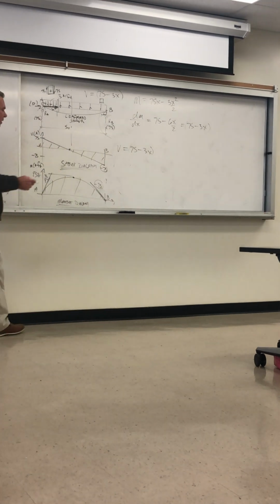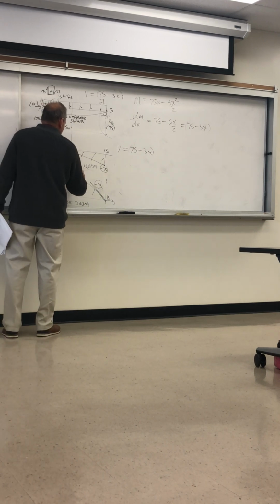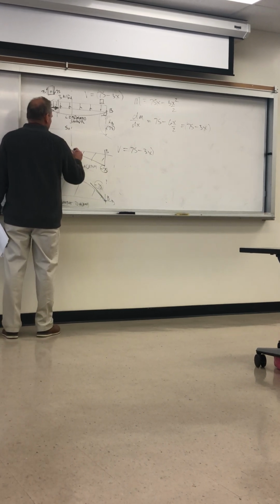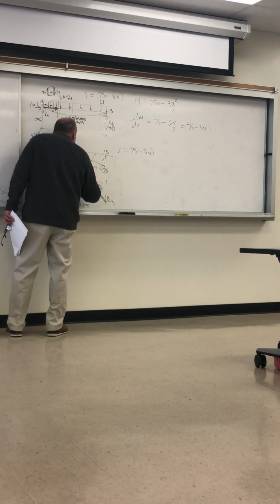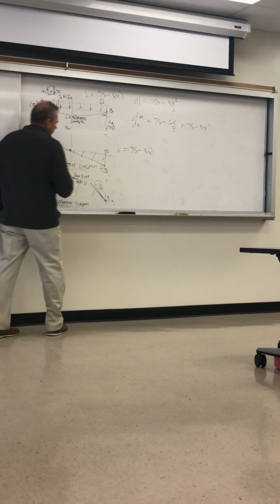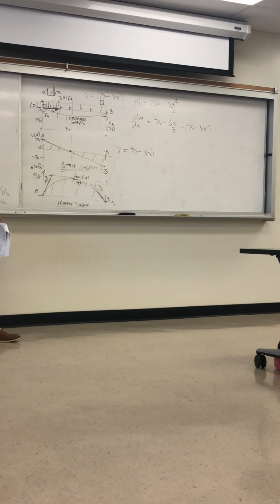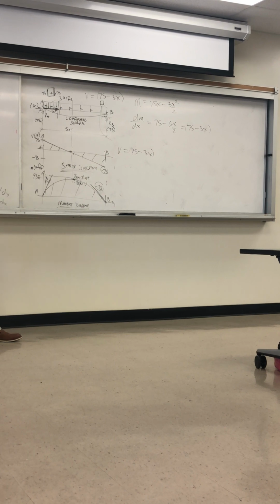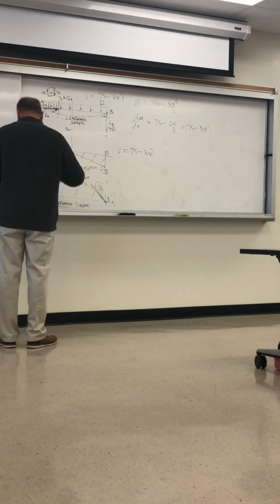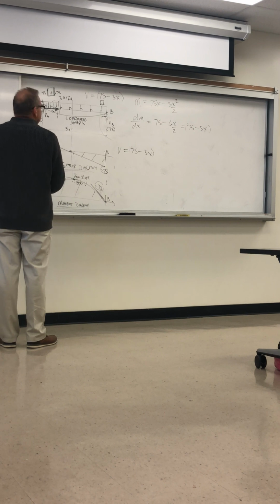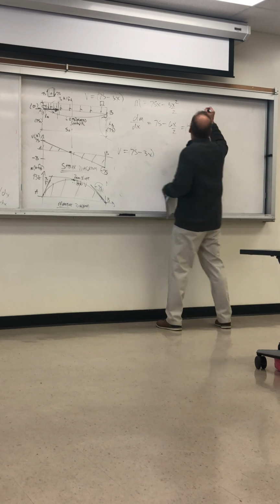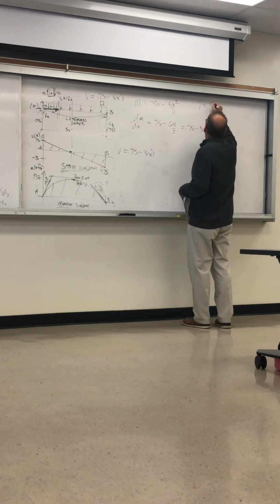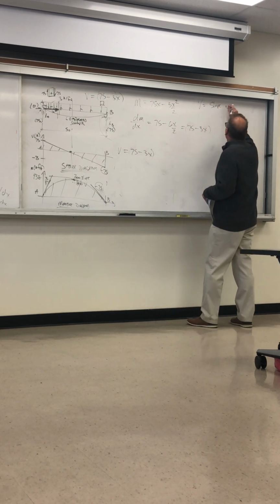Look at the center right here. These are at the same point. Zero slope, therefore zero shear. So the shear is 0 in the middle because that's the location of zero slope of the moment diagram. So we have, let's say, V equals the slope of the moment diagram.